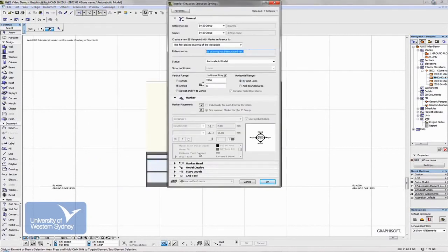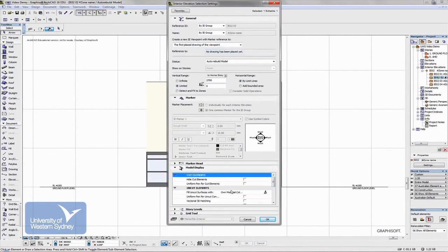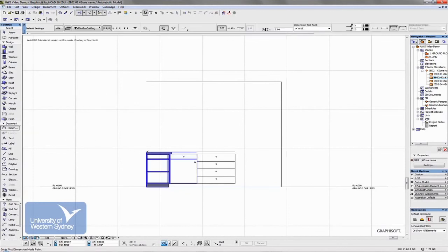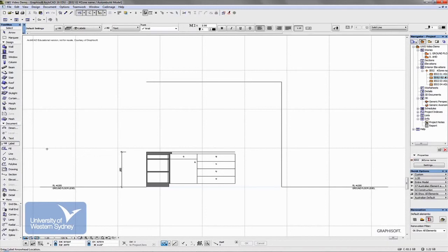So if you don't want color or other things like that, you can go into modeling and change that back so that I don't get color. But I can add notes now and dimensions, just like I showed you in dimensioning for the drawings. I can add those sorts of dimensions in. I can add labels, and I'll talk about labeling a little bit later, but you can add notes and dimensions and then save that as a drawing to put onto your layouts.